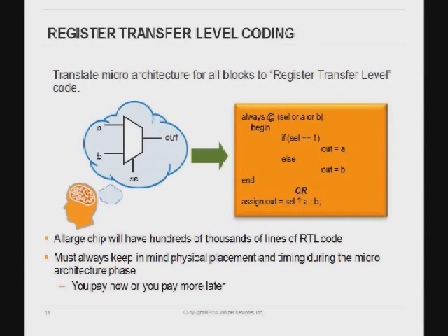So for example, one prominent difference between C and hardware: shift registers are very cheap in hardware because you just wire them differently. There's no logic involved, right? But a barrel shifter, which is easy in software, is not that easy in hardware because it's a multiplexer of many bits. So that's one example I would like to give. Keep in mind, those are hardware constructs, although they look like C.